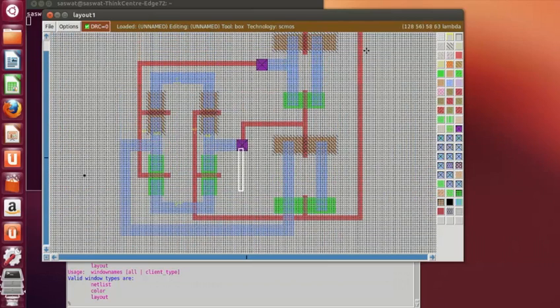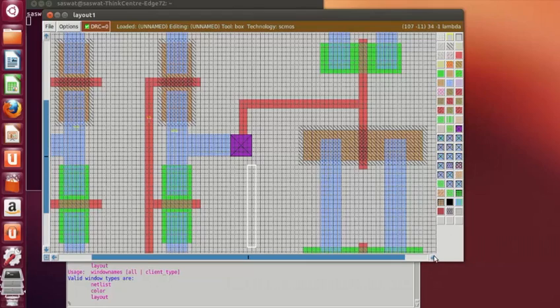Okay, this is connected to this gate. Actually B is connected to this gate, B bar is connected to this gate, the opposite gates that are connected. Then A is connected over here and A bar is connected over here. The output is obtained from these two drains.